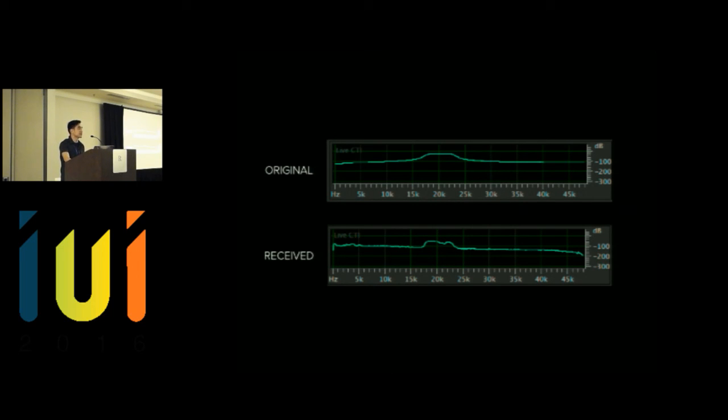Notice how some of the signal's energy has dissipated, and there's a dip somewhere in the 22 kilohertz spot. This change is caused by external surroundings and physical configuration between the speaker and the microphone. So in general, you have a frequency sweep that is generated by the speaker and that emits ultrasound from a specific range, let's say 18 kilohertz to 40 kilohertz.